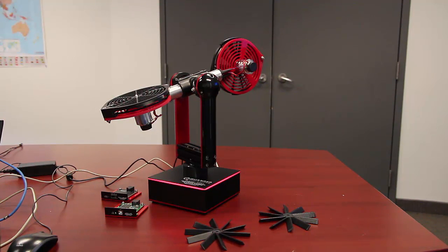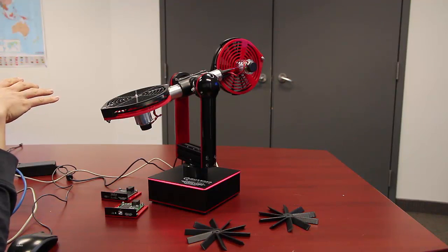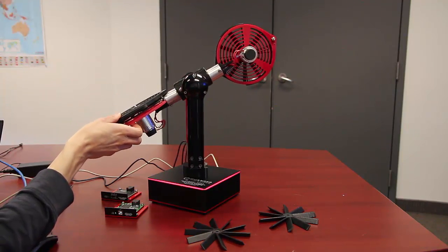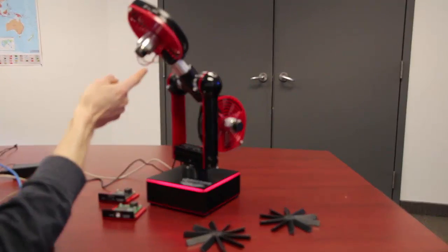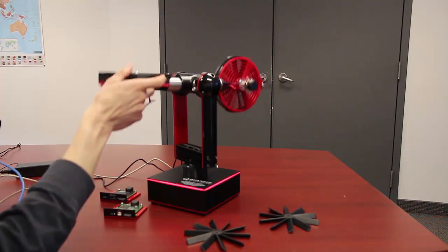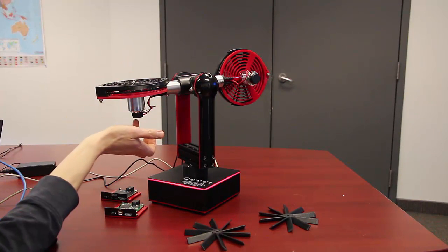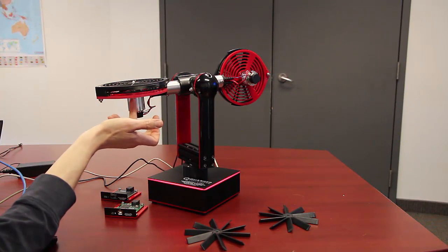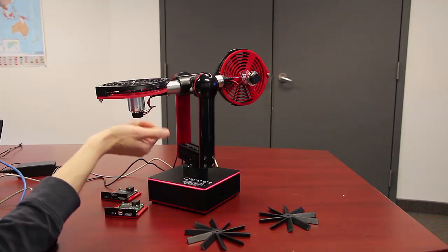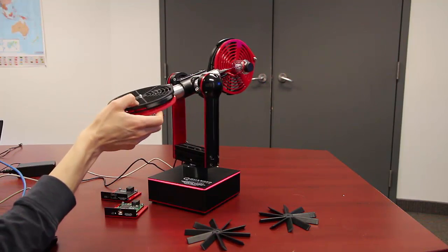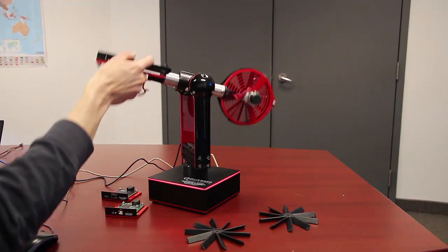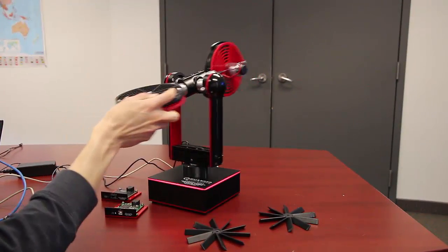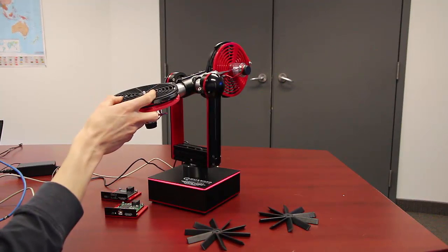Now let's talk about the sensors. We have a total of 4 encoders. As you can see, we have an encoder on each of the DC motors, so we have an encoder there and an encoder here. That allows you to measure the position of the DC motor, i.e. the rotor. And we have an encoder on the yaw and the pitch, so you can measure the position of the pitch axis and of the yaw.